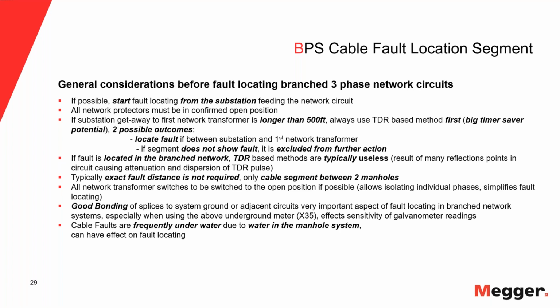So you have a pulse in one direction and a return pulse in the opposite direction. And when you measure the signal, you measure the difference between the two, and there is no difference, and you measure nothing. Now, you always will measure a little bit, but it could be that you measure a very low signal, which makes it very, very difficult. So the better the bonding in the system, you eliminate this issue.